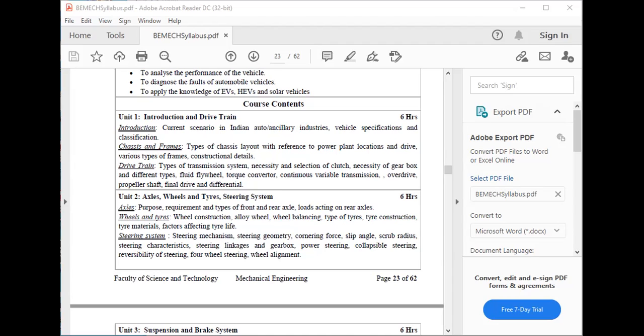And this is the diagram related to the centrifugal clutch. This is the total friction torque, that is, T is equal to N into mu into R into F minus P. This is the formula for calculating the total friction torque. Okay, this is the radius R. This is P, the force applied radially in inward direction. This is F, acting in radially outward direction. F is equal to m r omega square, where omega is the angular speed. This is the driven shaft, this is the driving shaft. All this is related to this centrifugal clutch.